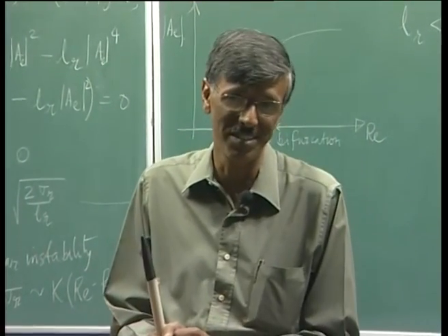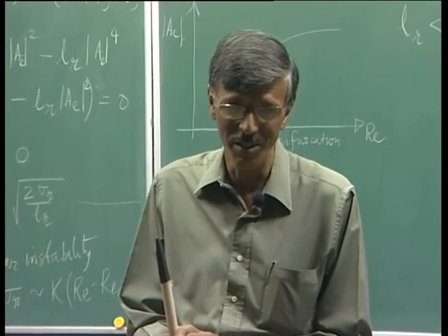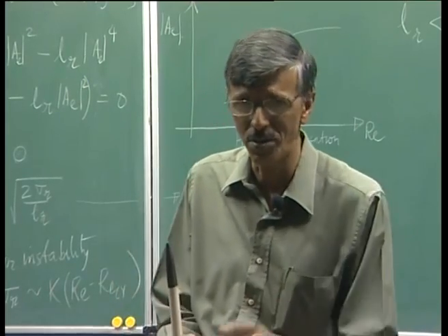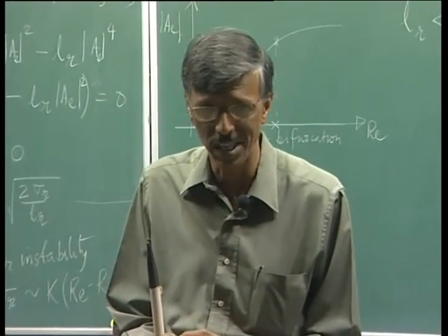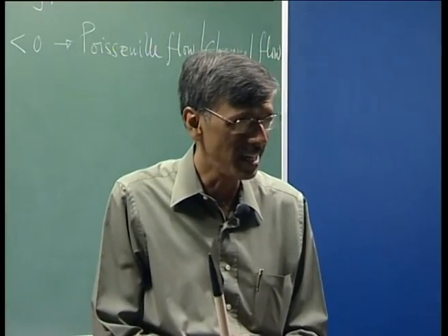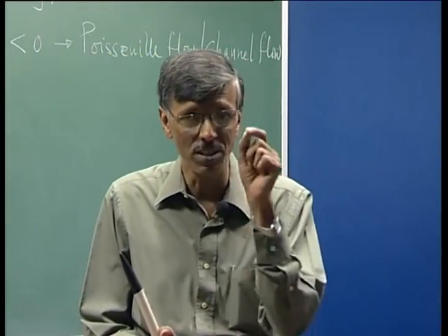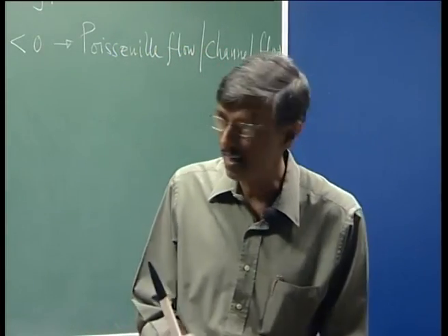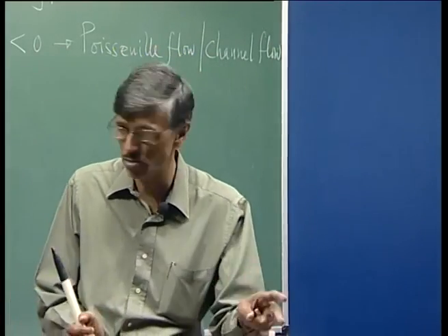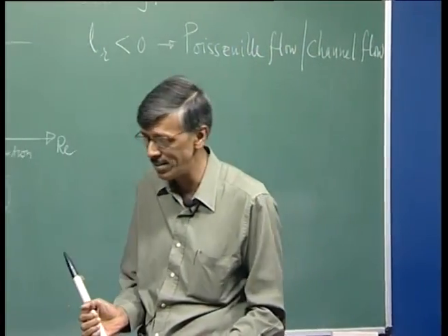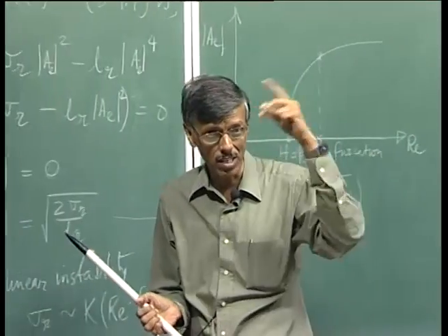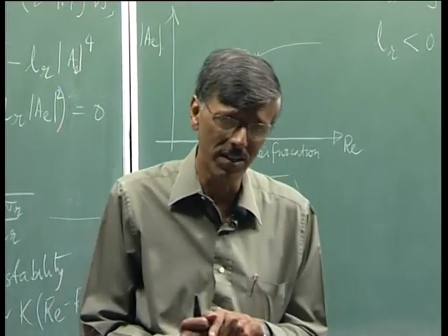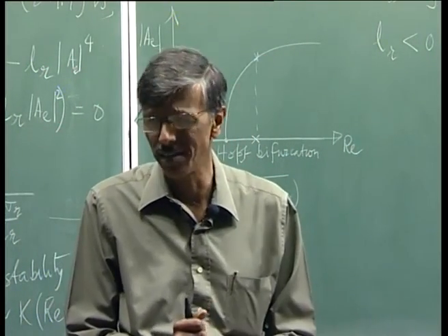and I told you about Kovasznay's experiment in the late 40s. When he put in a hot wire probe, he saw the vortex shedding disappeared. We talked about the subsequent work done by Strykowski and Sreenivasan, which investigated putting a smaller cylinder in the wake of a large cylinder and controlling the vortex shedding completely for a Reynolds number less than 120. It was shown experimentally in the late 80s. However, that started with the original observation by Kovasznay. When he put in a probe in the wake of a cylinder, the wake pattern changes.